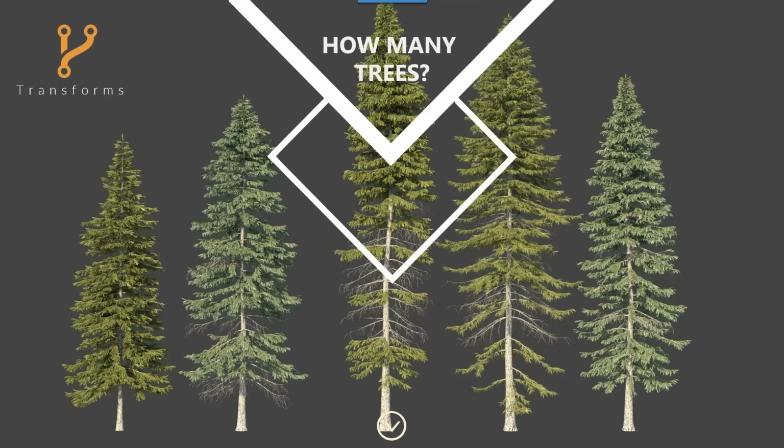There is, with parametric tree modeling software, the ability, of course, to keep randomizing the trees by just changing the seed values, which will give you a different tree. But often that results in trees that are only very slightly different. Far better to use trees like this, which are very different from one another, and then it will be much less clear if there's repetition. Because Forest Pack has the ability to hide quite a lot of repetition using transform randomization.